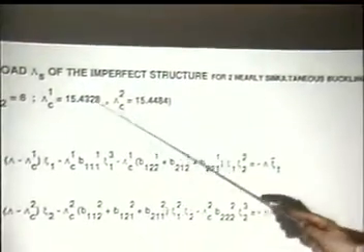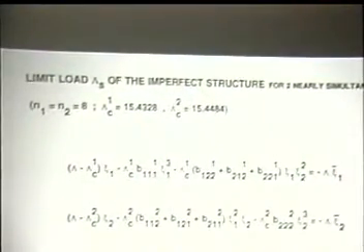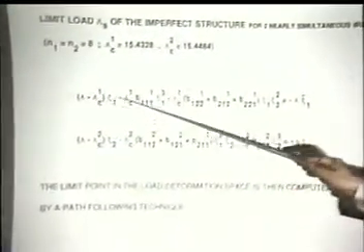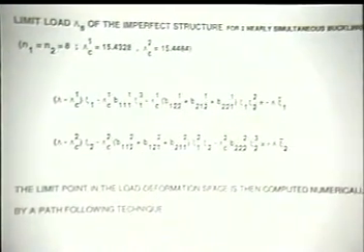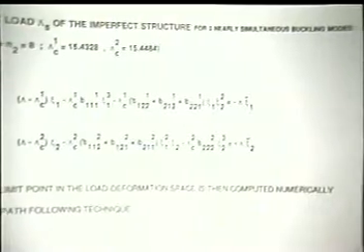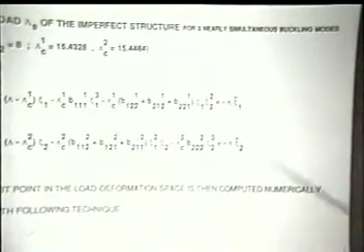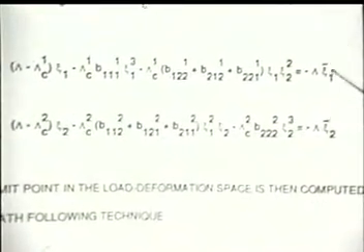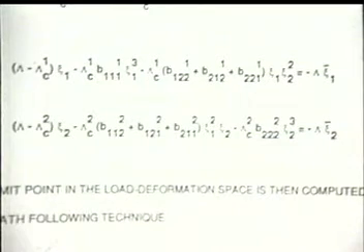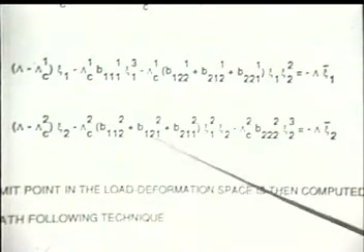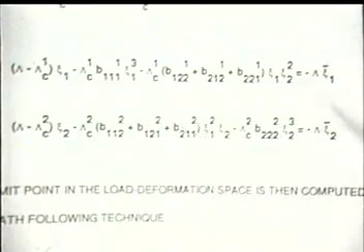Okay, so we have them. What you do then, here is the first one, here is the second one, very close to each other. Then you have two equations for describing their behavior in the lambda Xc1, Xc2 plane. And here, to make it a little bit simpler, we wrote it down for membrane pre-buckling. So the alphas and betas are 1, so their effect disappears essentially. These are the B's that were non-zero.